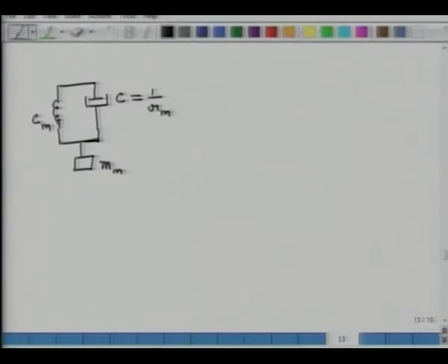We talked about it. So if you know the damping coefficient, you should be able to figure out what Rm is. And at this point, I am exciting it with a known velocity, so it is a source velocity. So then the question is, find the velocity of this moving mass. So what is this value? That is the question.